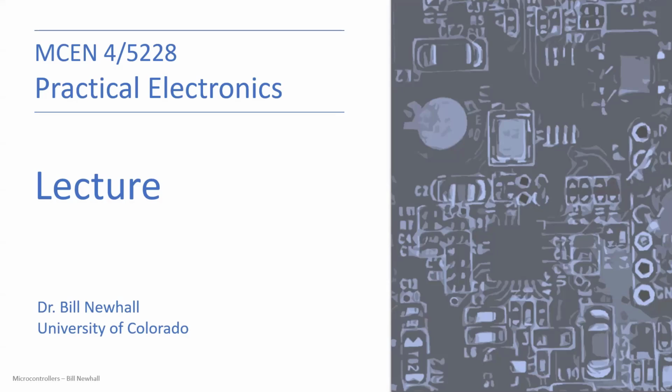So when you have logic circuits like microcontrollers, other circuits, sensors that have different logic levels, 5 volts, 3.3 volts, for example, you can insert level shifters in between, and I'll show you what that looks like. And we'll also start on analog to digital conversion, which is a very useful way to use a microcontroller with analog inputs to, again, sense and control.